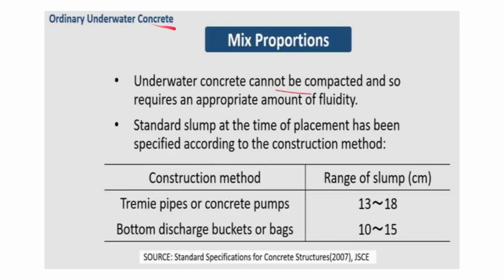In the case of ordinary underwater concrete, the concrete cannot be compacted, as we all know, and so requires an appropriate amount of fluidity. Standard slump at the time of placement has been specified according to the construction method as per JSCE, the Japan Society of Civil Engineers. So basically Japan has done a lot of work in this field.